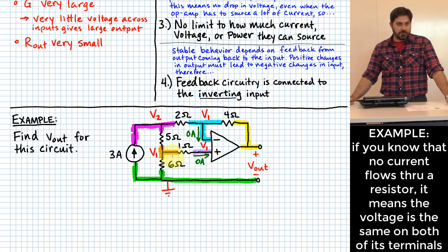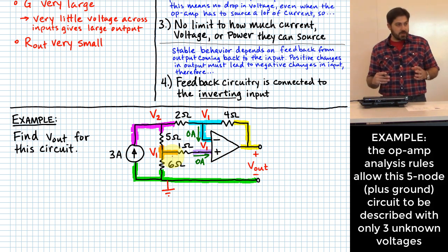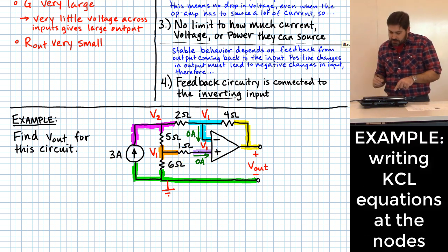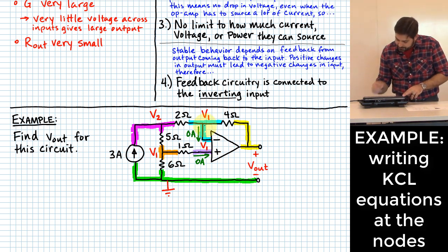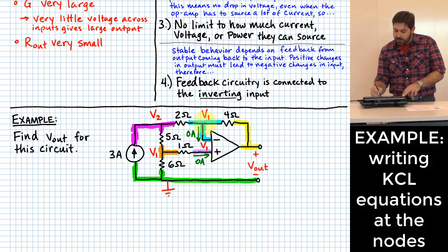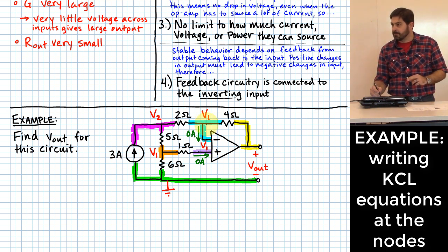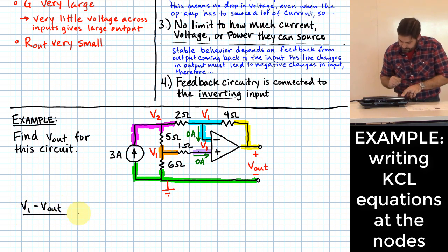Okay, so far so good? Now, this actually simplifies our process of working this nodal analysis problem a good bit. Let's start working this to see what it looks like. I'm going to start with an analysis of the aqua-colored node, and let's think about all the currents that are exiting the aqua-colored node in a nodal equation. How do we do that? Okay, we'll start with V1 minus V out over what? 4 ohms.